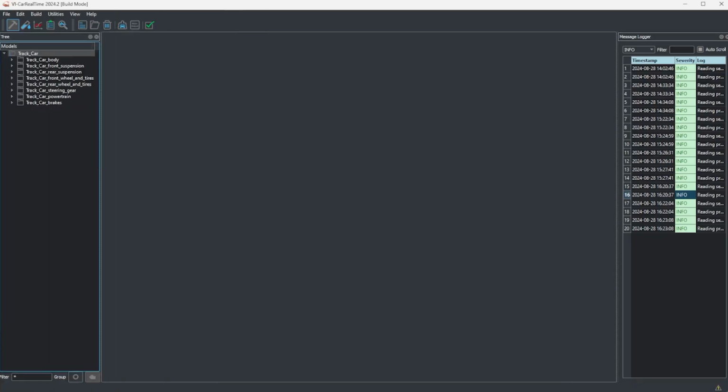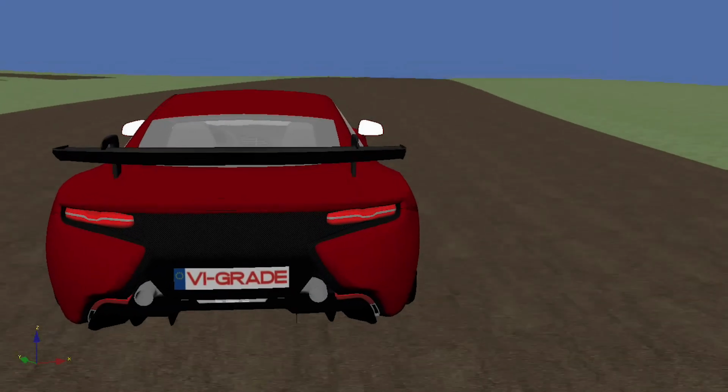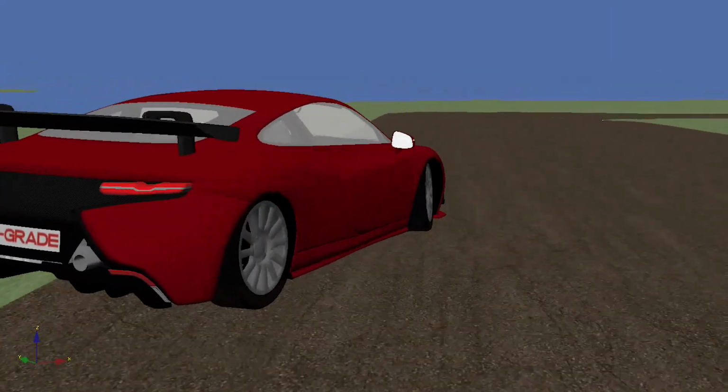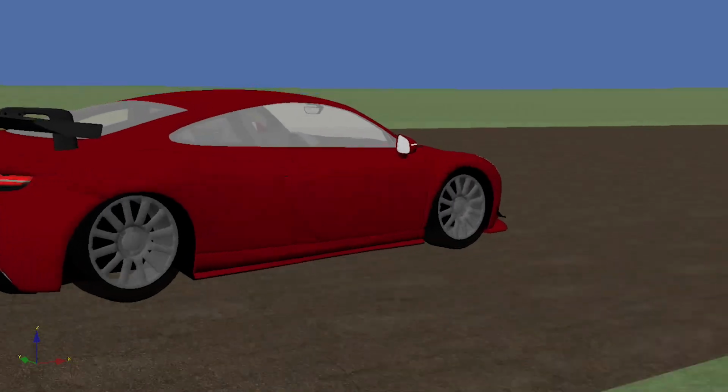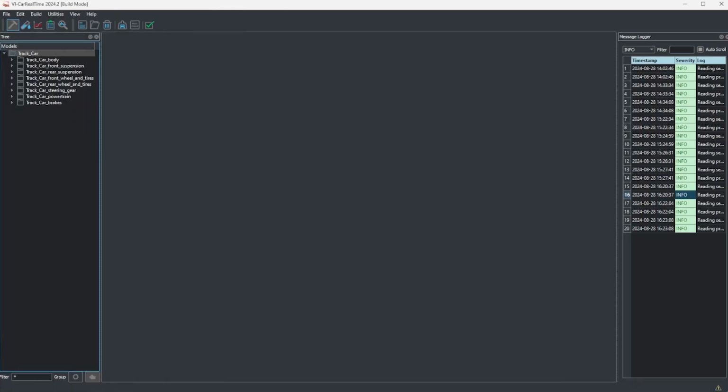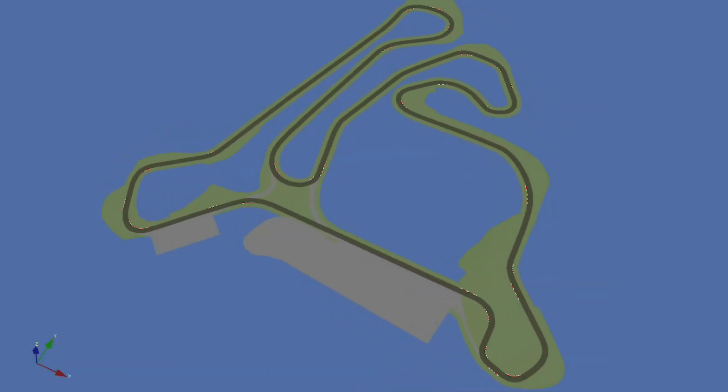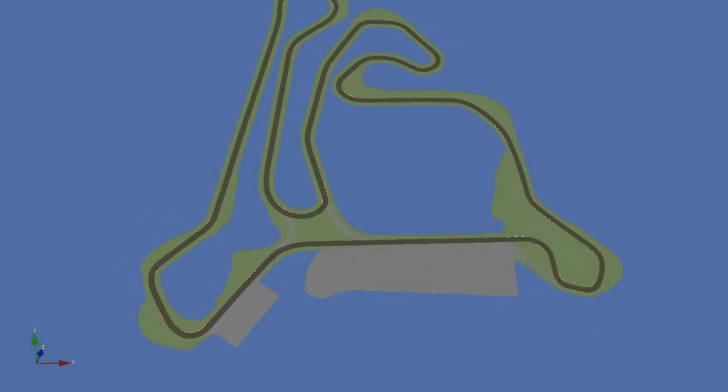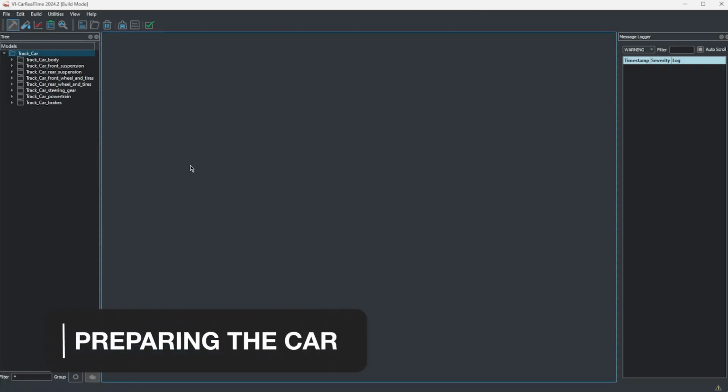Typically, going as low as possible is desirable to maximize downforce and minimize drag. On the other hand, going too low may cause the car to heavily rely on the bump stops and maybe bottom out too much, both sacrificing speed and damaging the underfloor when hitting the asphalt. In order to find the right trade-off, we will run a series of tests on a racetrack. We will understand how low we should go on each axle. Let's start by preparing the car in build mode.